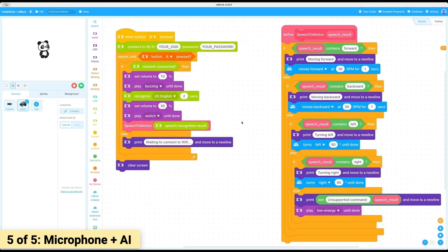One final note here is that because the speech recognition can take some time, the code will block here before it can continue until the speech recognition is complete. If we want to end the program while this is happening, pressing button A will not have any effect because button A press is registered and detected only when we complete the loop and then get back to the beginning of the loop again during the next iteration.